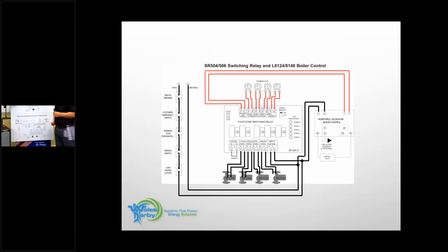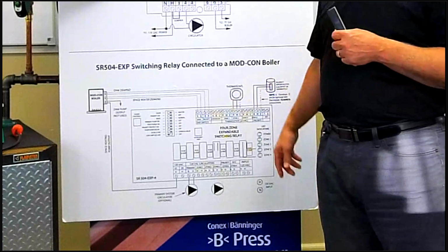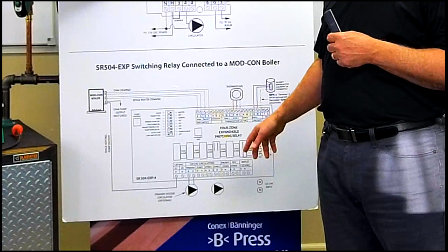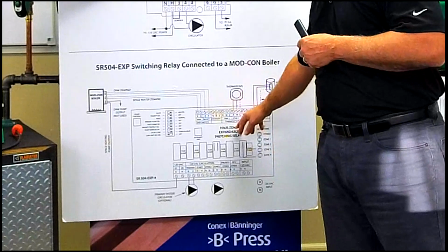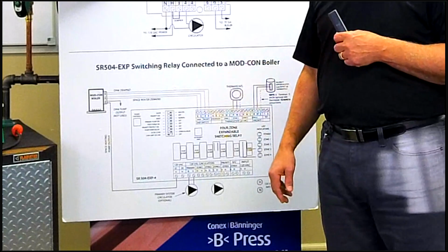I would take A to A, B to B, C to C. I would do that with standard thermostat wire. I would set that to master on the primary. The second one would be the secondary. It says slave. We would set it to slave. Okay. And now all communication between the two boards happens, and my primary or master, that end switch is what's going to turn on the boiler.